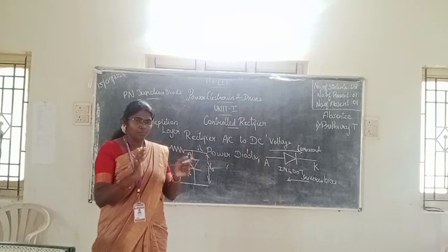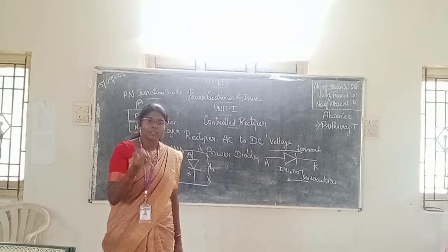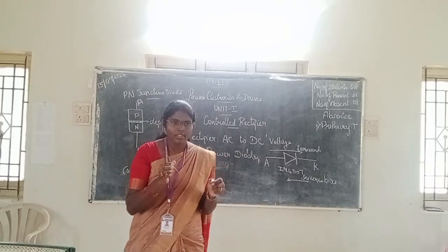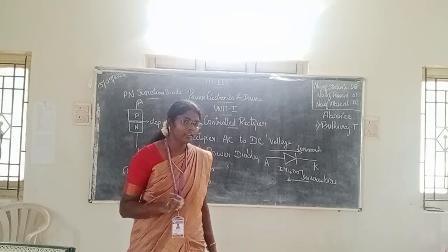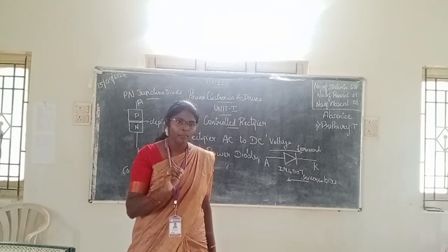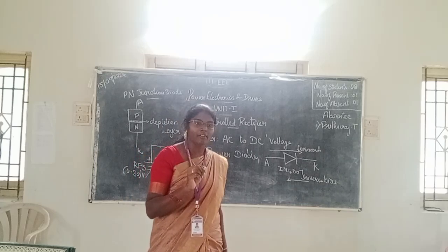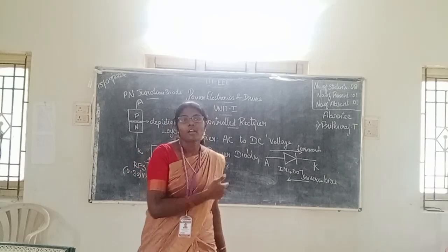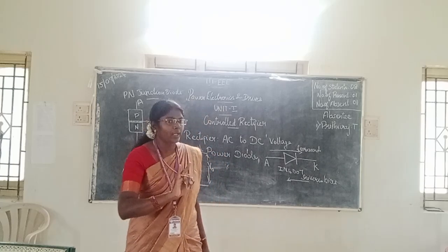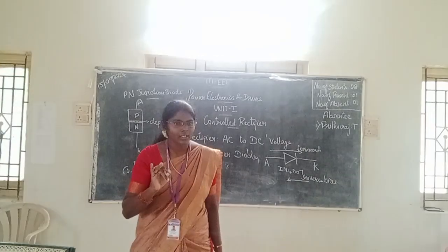Inside there will be chip boards. On the boards, there will be small electronic devices: capacitors, diodes, or other small electronic devices. Everything will act on DC. The voltage ratings are very minor, so for those particular devices we are going for the diode rectifier. The application is what they said: the supply is AC, I step it down using a step down transformer, and by using a diode rectifier I am converting it.